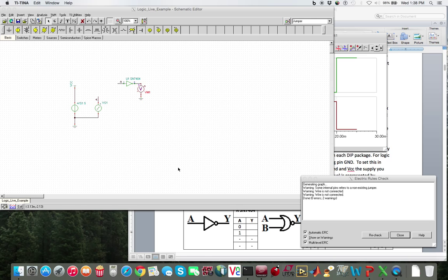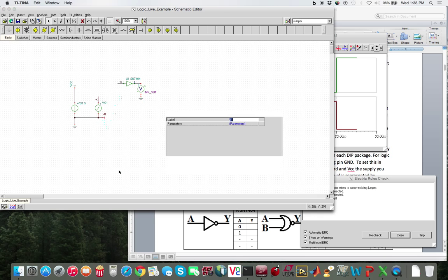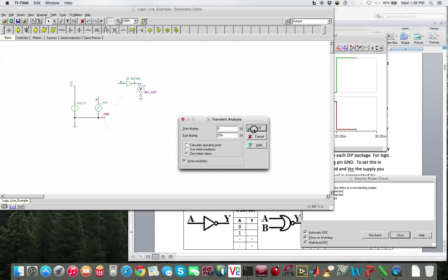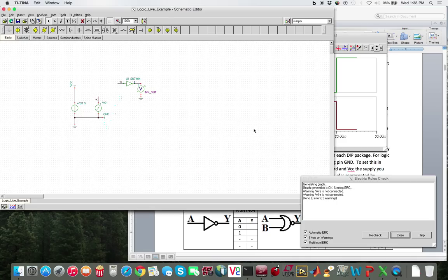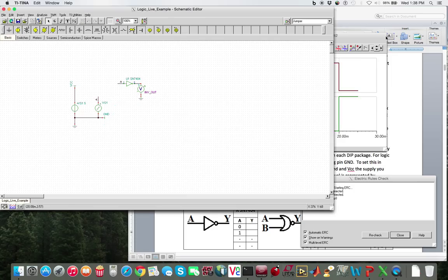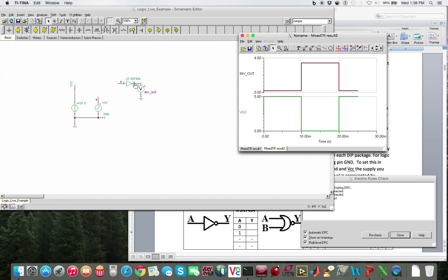Okay. So let me fix that jumper problem. So go ahead and drop down a jumper, and go to properties and call this ground. And I think this will work. So now if we simulate it, analyze transient, and run it. So, yep, okay, now it's working just fine. So I think one of the problems is it's looking for a ground for the inverter, and so it's looking for a jumper. So anyways, that works.